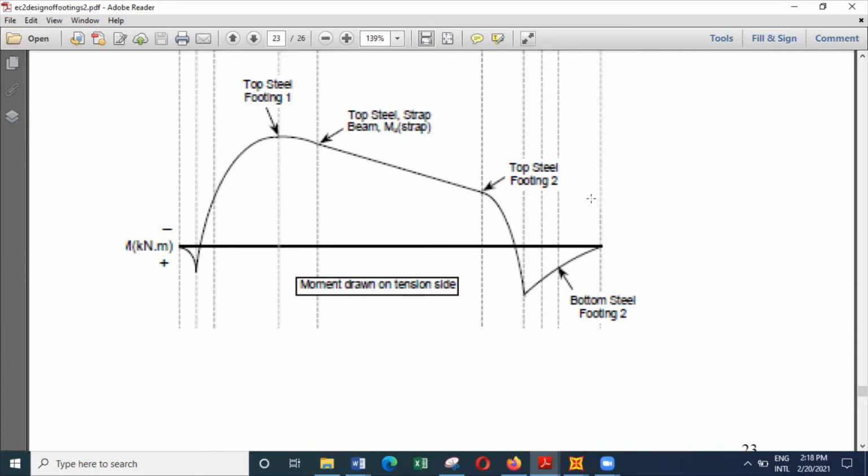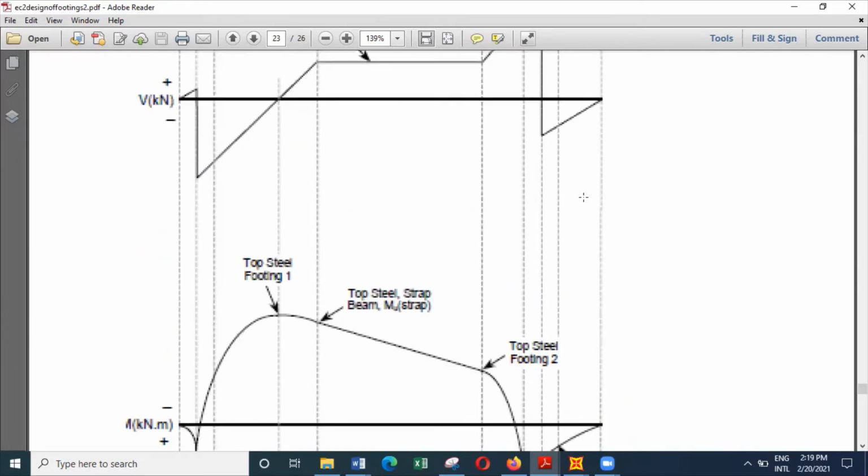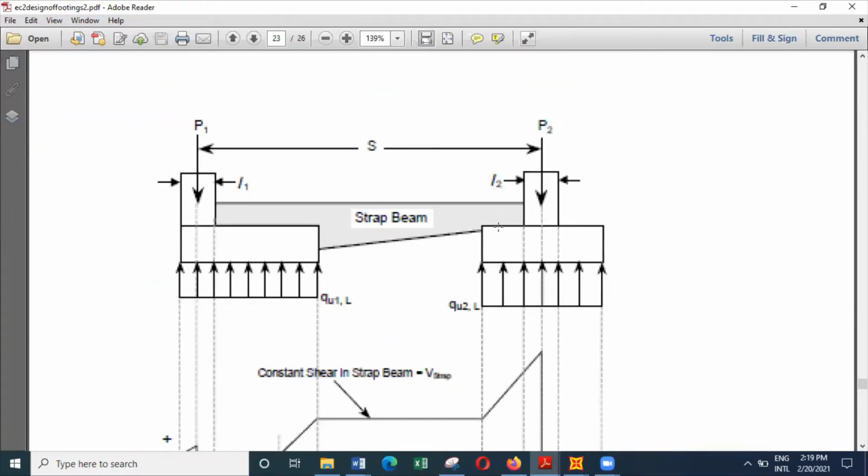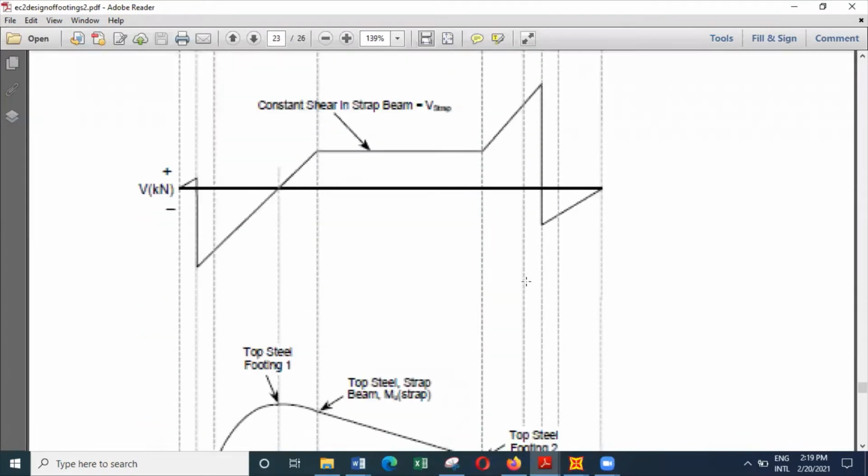And also we have to check for shear, which is the vertical shear and the punching shear. So if you look at this situation, there's a possibility for some punching shear failure in this heavily loaded column if the thicknesses are the same. So you may have to look for punching shear and direct shear failures, and select a thickness for the footing so that this direct shear failure can be withstood only with the use of concrete, without using any reinforcement.